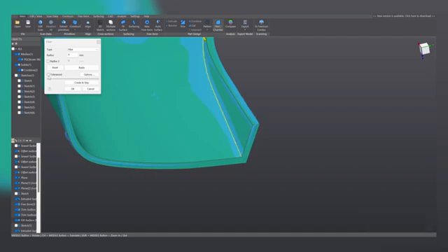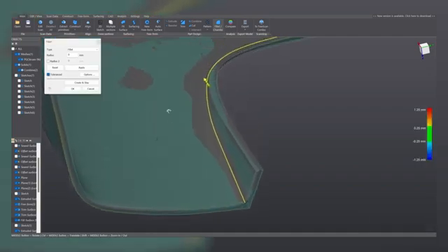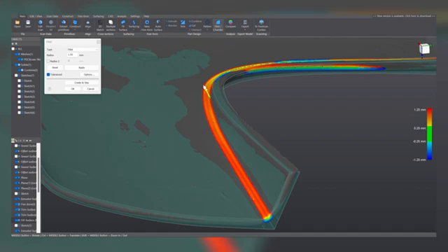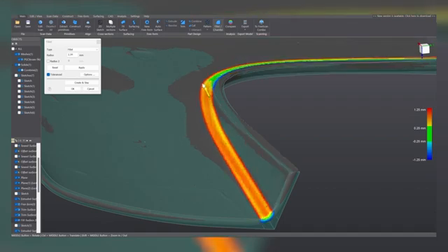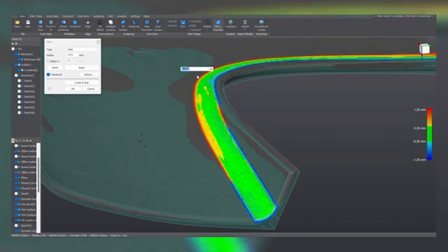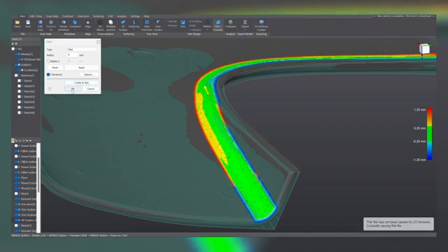And I recommend you to use the tolerance tool here. With it, you start dragging this arrow, and you can see live how the tolerances result evolves as you change the value of this filleting. Right now, we start to see our green color. So let's try with a 6mm radius for this fillet and click on OK.